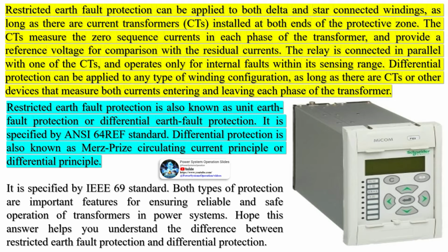Differential protection can be applied to any type of winding configuration, as long as there are CTs or other devices that measure both currents entering and leaving each phase of the transformer.